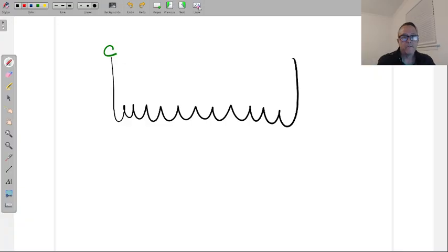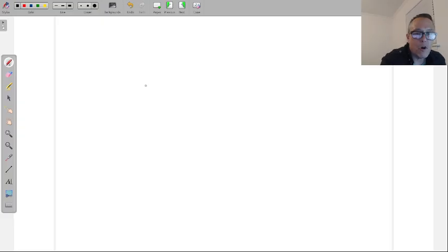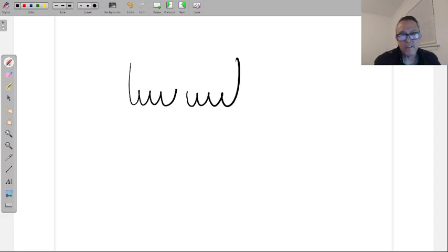So transformers are built in two ways. Again, there's different voltages that can connect to the primary, different voltages that can connect to the secondary, etc., but they're only built in two ways. Either the windings are like this, one solid winding, or the windings are split in half. And this is called a split phase winding.